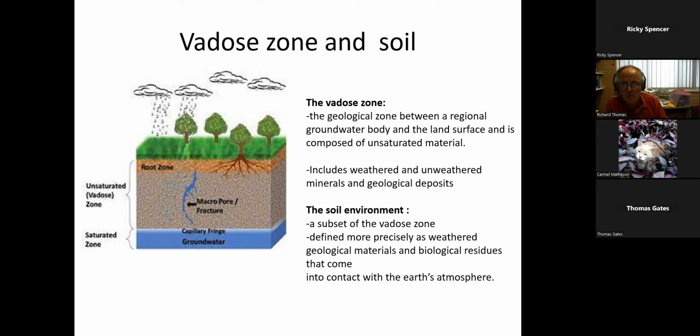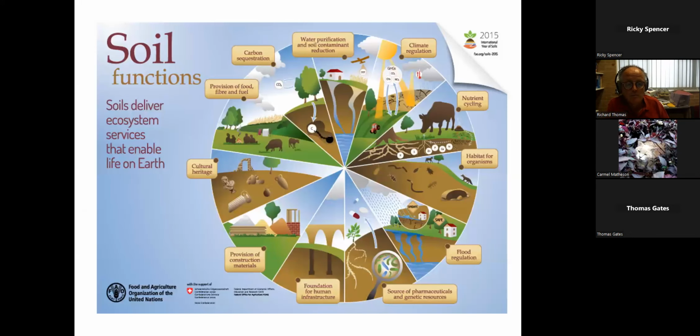There's not really a reducing zone. If you're looking at more waterlogged conditions, and I come from Europe, you'll see that the soils are darker, kind of bluey red color. Some of them are a deep dark brown color. That's because they contain mostly iron 2 minerals, and that's because less oxygen can get into the soil. So the color of the soil will change depending on how much oxygen and water gets into it. So it's all weathered materials.